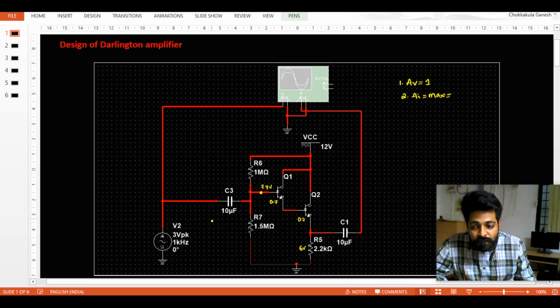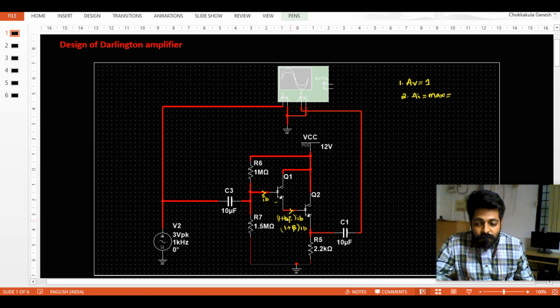Practically, through observation, the transistor over here will be taking IB, amplifying it, and generating the current over here, 1 plus HFE times IB, or in a few cases we represent beta as HFE. So it will be 1 plus beta times IB, and approximately beta times IB.